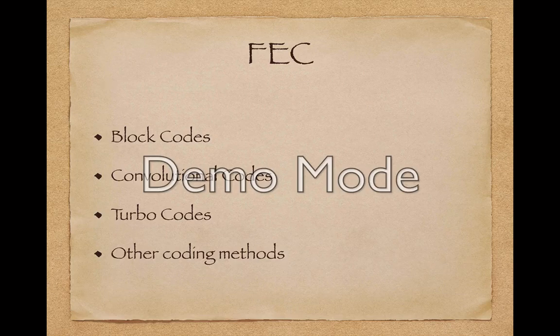And FEC can be divided into a lot of types. Mainly are block codes, convolutional codes, and turbo codes, and other coding methods. Block codes work on fixed size blocks, and convolutional codes work on bit streams. Classic block codes are usually decoded using hard decision algorithms, which means that for every input bit, the receiver must decide it is a 1 or a 0.